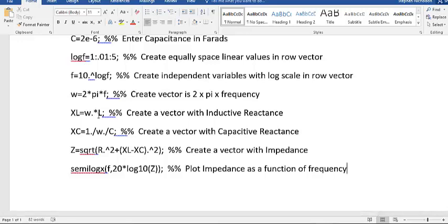There's only one inductance value. And then I also take every value in this W matrix and I divide it by the capacitance. So these are matrices, and you've got to use these special commands when you do matrix operations. Likewise here, R is a matrix, so instead of squaring R, I square it with this little dot, which means I'm taking every element of that matrix and squaring it, not squaring the actual matrix. I'm not multiplying the matrix by itself. I'm squaring everything that's in there.